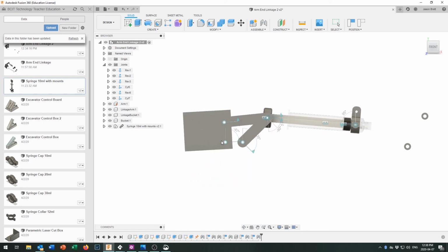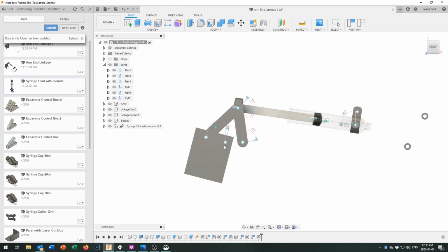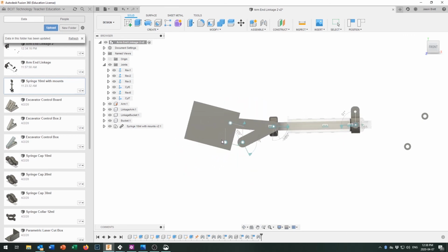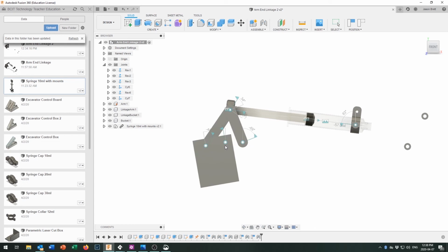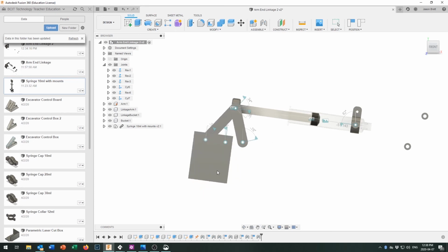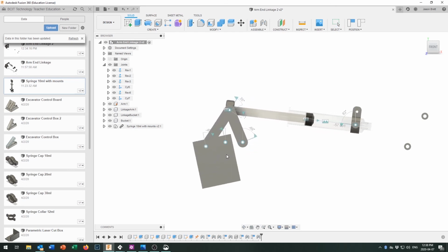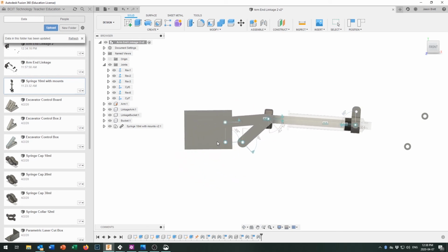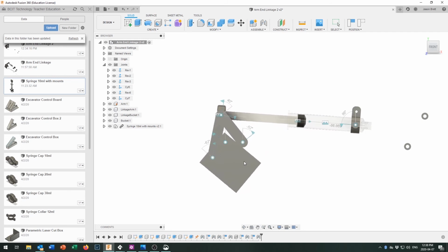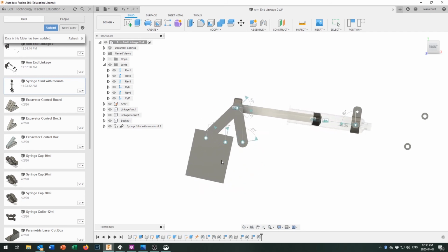Now, one of the things you do have to watch out for when you see huge amounts of movement in the bucket and very small amounts of movement in the plunger is that there's always a trade-off of distance and force. So if that plunger is moving a very small amount and you see the bucket moving a very large amount, then you probably don't have a lot of force being transferred to the bucket at that point. So the idea is to try and keep the movement on the plunger nice and smooth as the bucket moves back and forth.